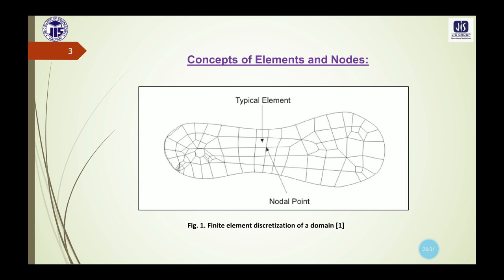And these nodes are assigned at a certain density throughout the continuum of the domain, depending on the anticipated stress levels of a particular domain. The regions which will receive a large amount of stress variation will usually have a higher node density than those which experience little or no stress. So the discretization or node density is also very important to accurately grasp the sudden change in the different parameters.